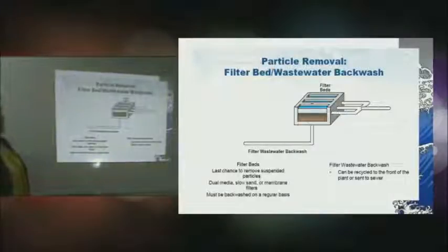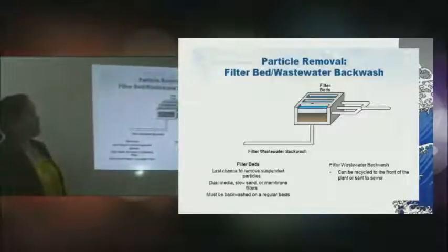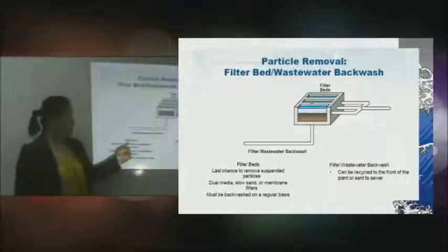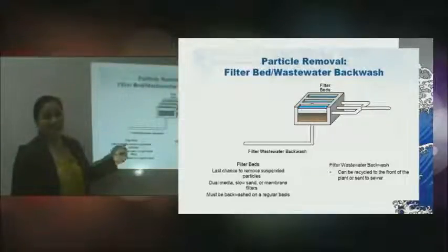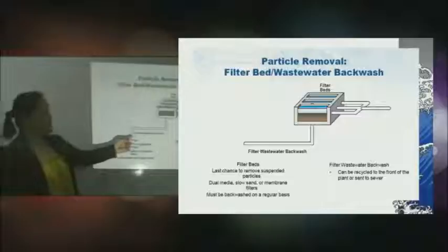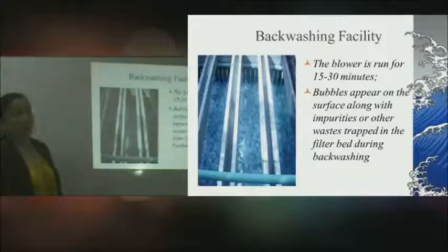This is a typical filter bed with a wastewater backwash, because you all know that your filters would need to be maintained. Therefore, one important design feature of your filtration bed would be the backwash, so that you can recycle the water to the front of the plant or send it to sewer.